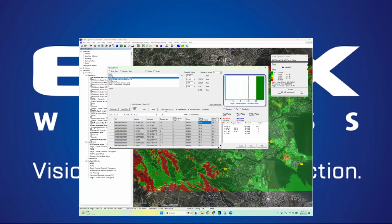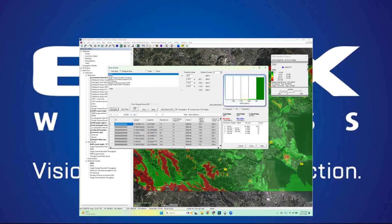And of course I can export all of this to CSV as well. So if I want the answer for every fixed subscriber location, and they've all got different heights and they've all got different equipment types, well, that's fine. I can set up a multi-point study, run the design criteria that I want to see, and then export this directly to a CSV.